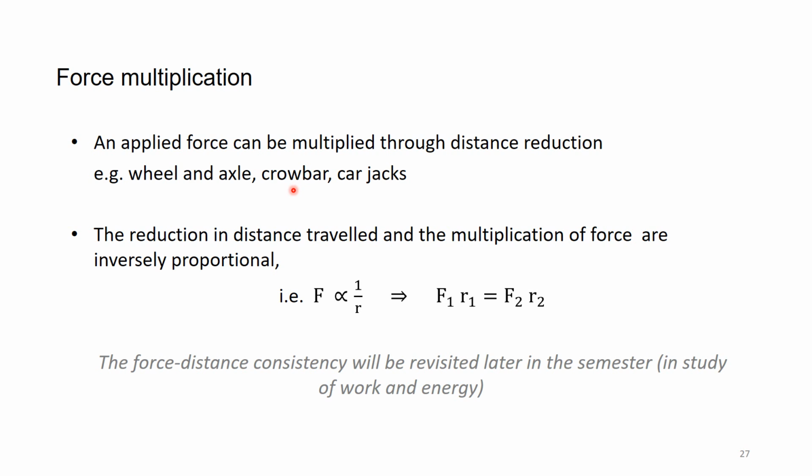So every time you turn the handle, you're covering a big distance around the circumference. And on the other side, it produces a big force on the car, but lifts it a small distance, okay? So you can see the relationship here. You're providing a small force over a big distance, and you generate a big force over a small distance, okay?